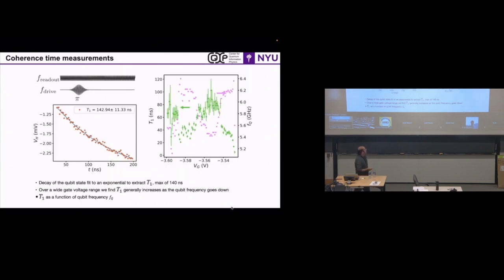The other thing is, if I can change this by gate voltage, that means my frequency, I can change it. I can change my T1. And if things were proper here, I can say, oh, look at this part. The frequency is not changing much here. I have a sweet spot, right? Basically, the first derivative is 0. So here, my T1 should be highest. Oh, it is highest, but it's not as high as I want it to be. So there are also these sweet spot games that you can play with gate voltages, pushing your times up as much as you can.